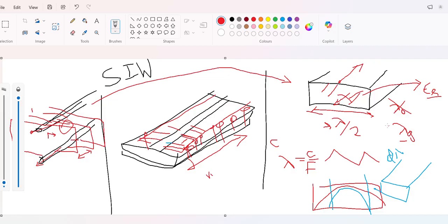Now, the dielectric filled waveguide was already solving the problem, but then you have to fabricate a metallic box and fill it with the substrate. Here we are utilizing the low cost PCB making processes and just converting it into a waveguide structure, and that is how it becomes substrate integrated waveguide.